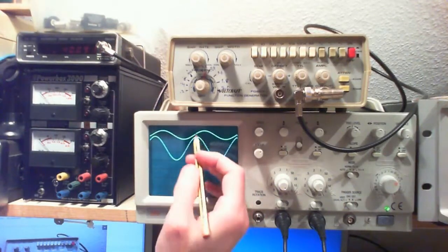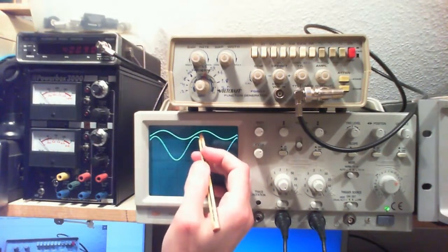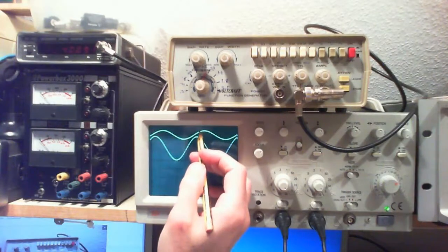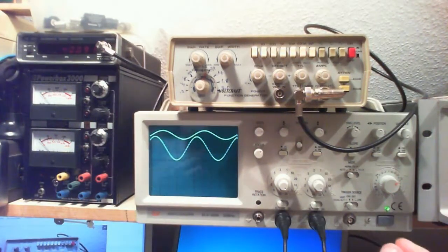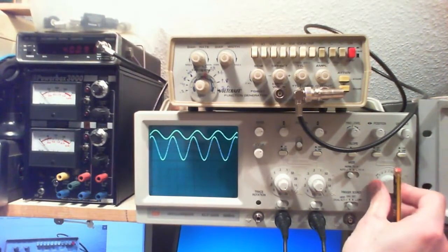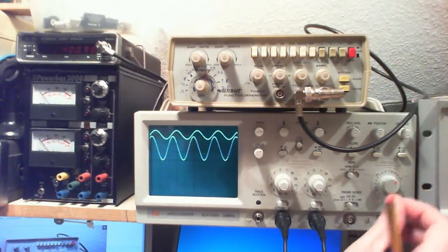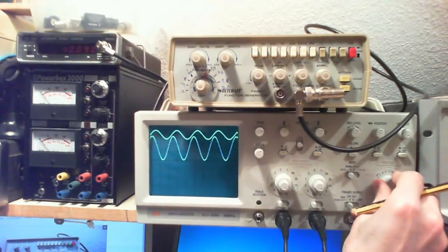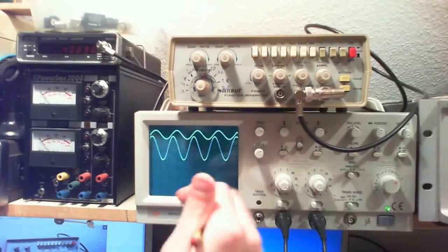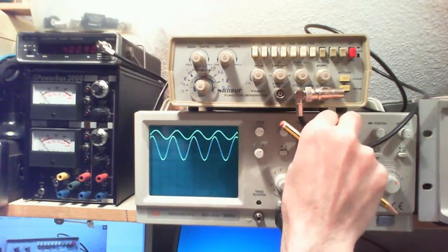I don't really know if I'm supposed to take it there or a little bit to the right or to the left, so I have to go back in speed. For example, right now I'm on 5 microseconds the time base, so I go to 10 microseconds. Okay, so at 10 microseconds I can kind of see the peaks here. This is about the right place to be.